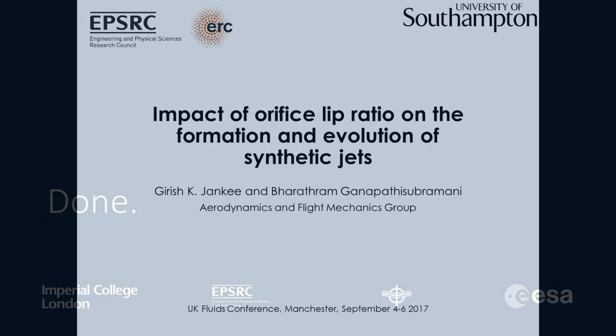You've looked at that constant angular attack. Yeah, that's a big issue, of course. Satellites will tumble. But fortunately, they'll tend to have modes in which they like to tumble. So for a cylinder, it might be an end-on mode or a spinning mode. And so you can build up an idea of how the heat transfer changes with the angle of attack, then you can develop a model for the tumbling modes. But yeah, that's a difficult problem.